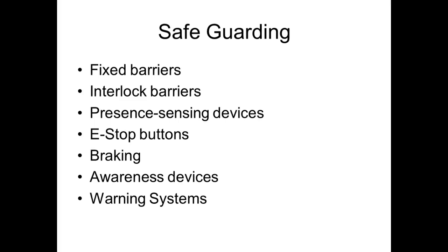So you'll see that big old robot, if I hit the E-stop, you see the boom. You check around a lot. It's got a lot of mass, a lot of inertia, which could cause it to do what? Could cause it to lose load. Because if the load's in motion and the robot comes to a hard stop like that, it could actually lose the load and you could get people hurt. You mean the load, meaning the whatever? Whatever is moving around.